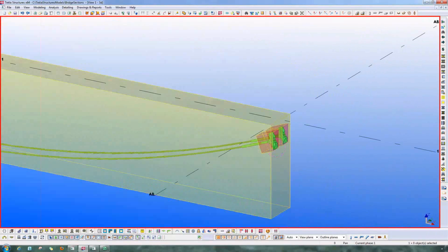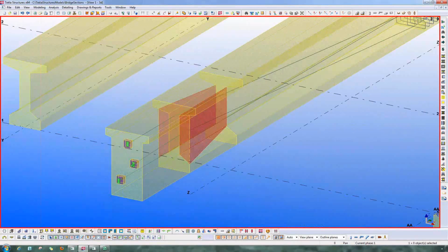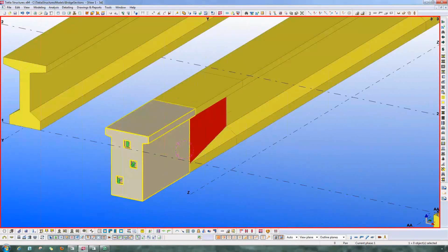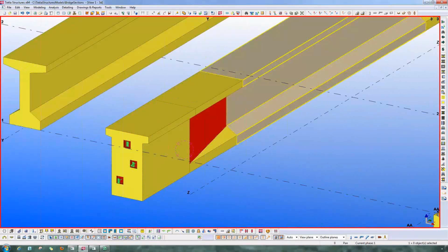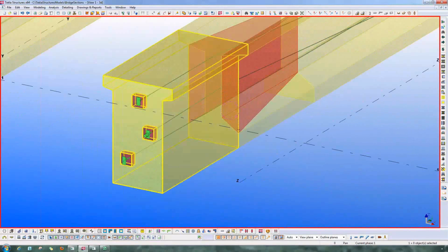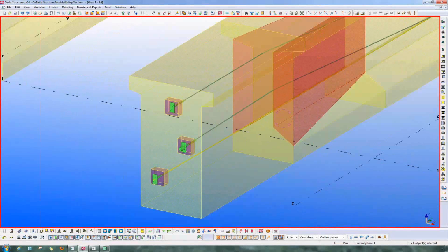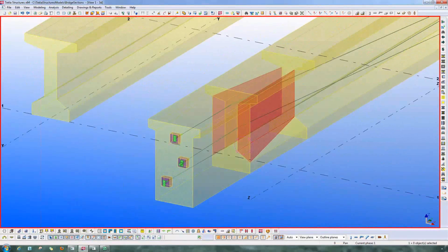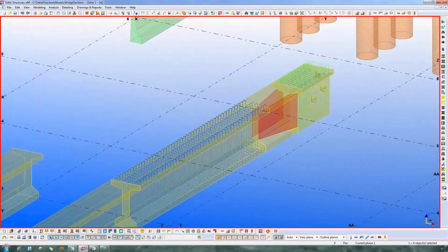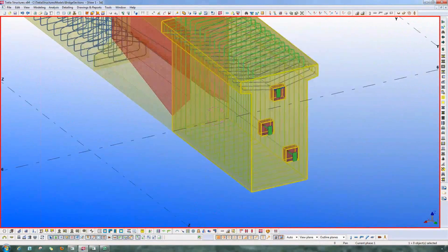the end block details. And coming to the I section girder here, where I have the varying section and even the different sections over here, we can check the post tension information modeled with the end block details. So here the tendon is 3D profiling. That means it varies in X, Y and Z coordinates. So accordingly the tendon is modeled, and even the regular reinforcement, what we see in such I section girders.